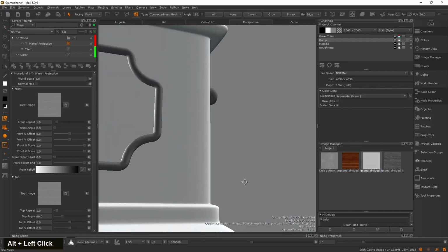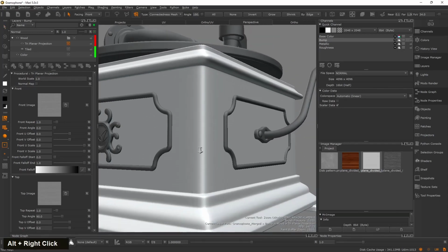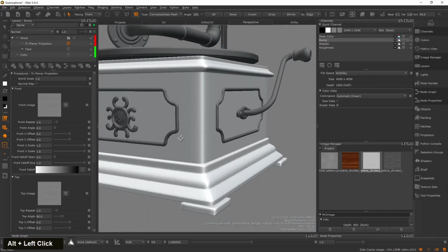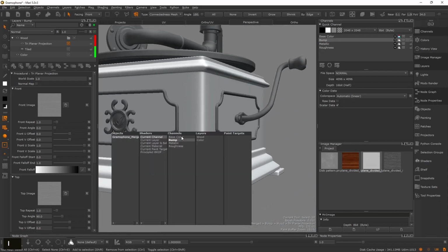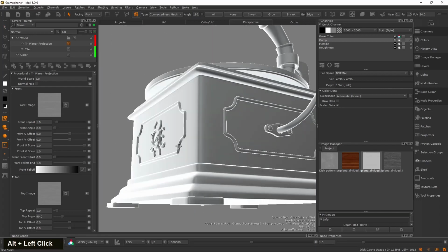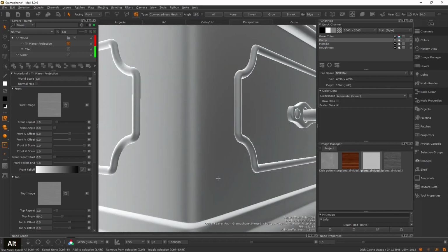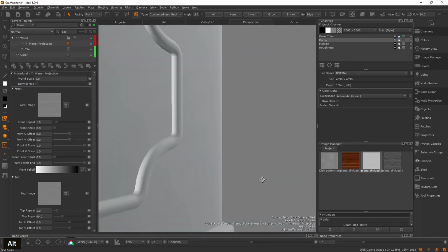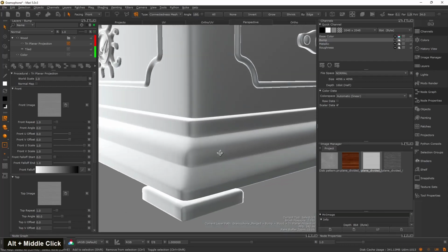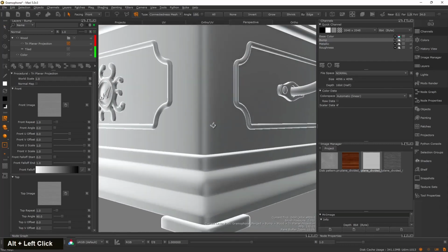let's see our new creation inside the shader with the Principled BRDF. So let's hold I, go to shaders. We are seeing current channel bump. So let's change that to Principled BRDF. Let go, wait, and as you can see, the whole shader is loaded. We have a little bit of bump going on.